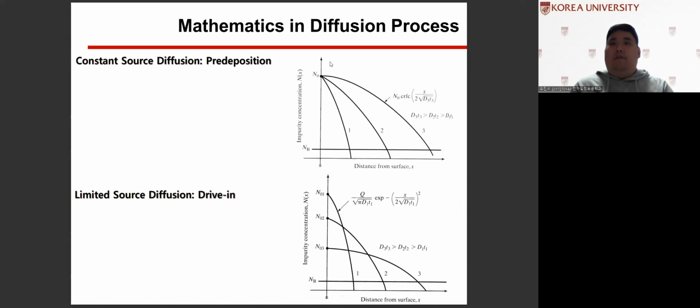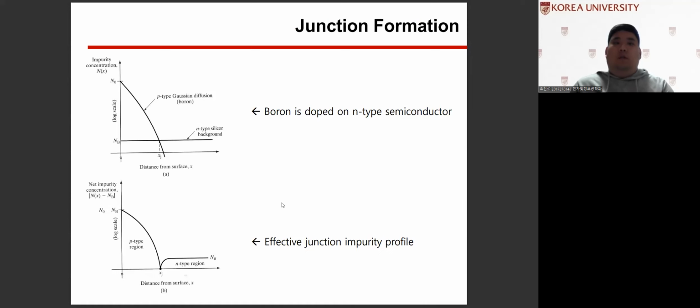After we apply the dopant, we can drive in heat to make the diffusion go even further, and the graph looks like this from N01 to N03. Normally the wafers are doped with a background dopant, so we can draw the plot, and the point is that where the dopant we apply meets the background dopant, this is the junction.